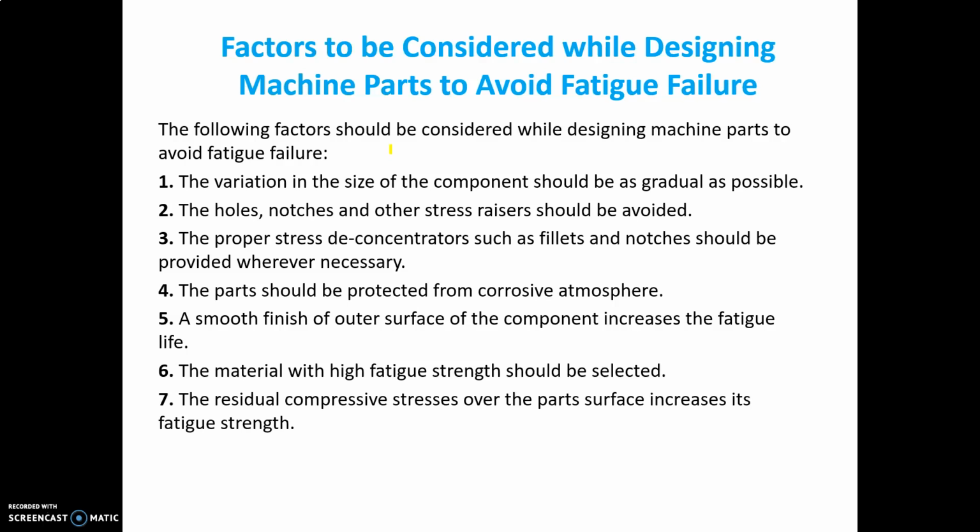Now, factors to be considered while designing. These are the 7 factors which should be considered while designing a component based on fatigue failure. First, the size, that is the variation in the size. Then the holes and notches should be avoided, or stress raisers should be avoided, or we should follow the stress concentration remedy methods, the proper stress deconcentration, such as fillets and notches, which I already told.